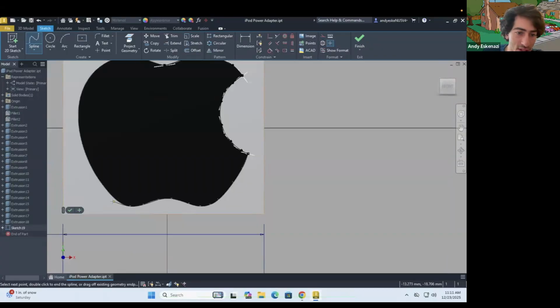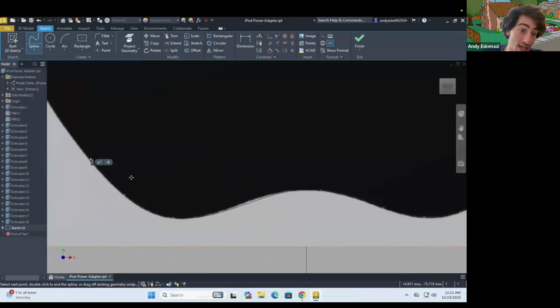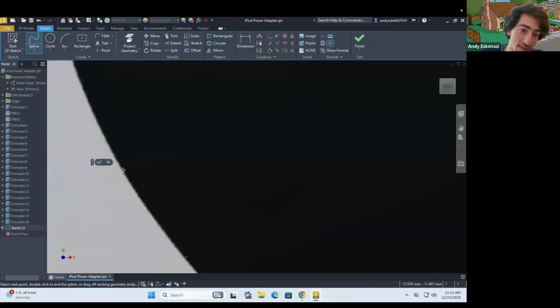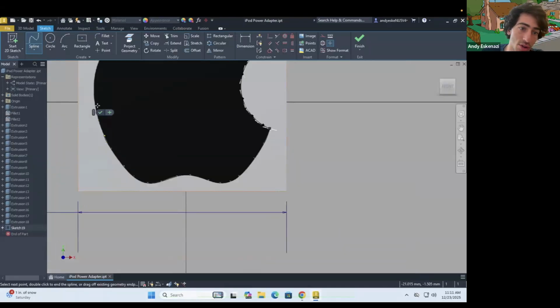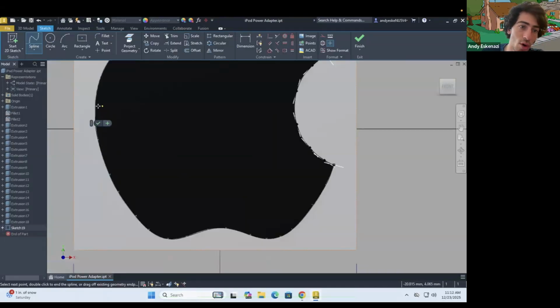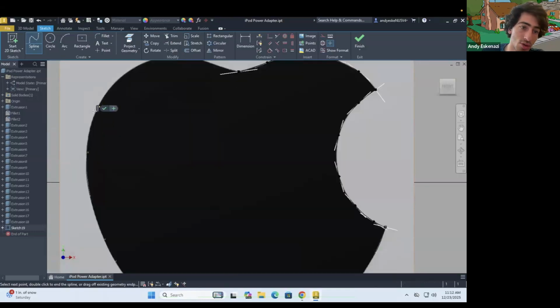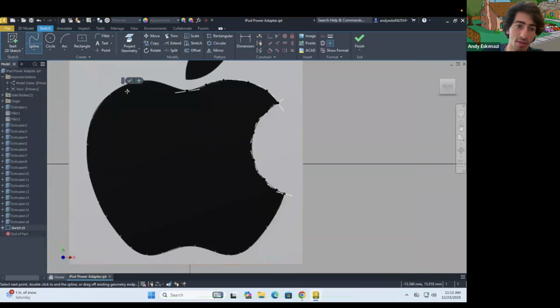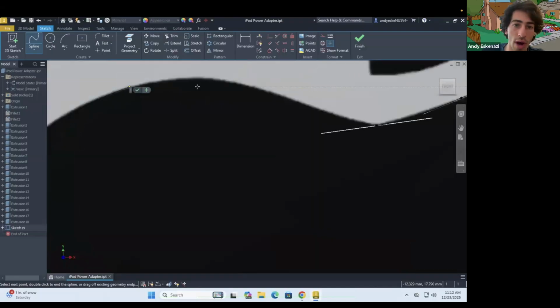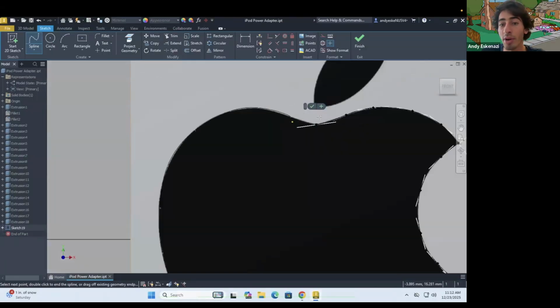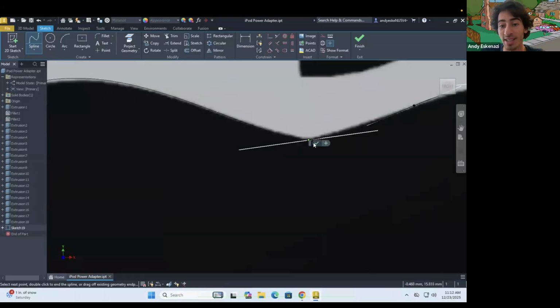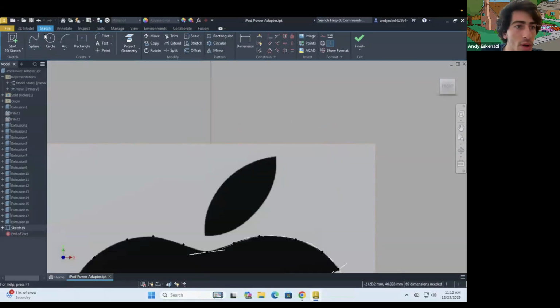And this is just the beginning of our journey using splines, because we'll be using splines extensively, especially on the following session where we start to use it to trace objects. That's literally all that we're going to learn in session two, is that we're going to do it super extensively, taking what we've learned today on session one and combining it to do super crazy things. Again, it's a surprise. We got that, and now we're going to do a 3-point arc where we select that point, make it all the way like that, and another 3-point arc that's going to go all the way like that.